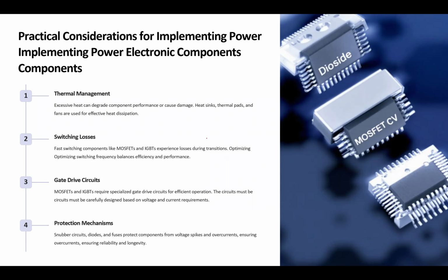So when we talk about the MOSFET and BJT, not only do we have to have those components, but we also have to have a control circuit to create the signal for the gate in order to get what we want. And we have to have a protecting mechanism. One purpose is to avoid those breakdown or saturated current situations.